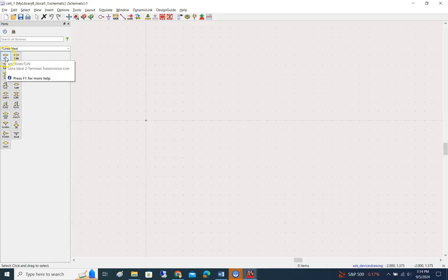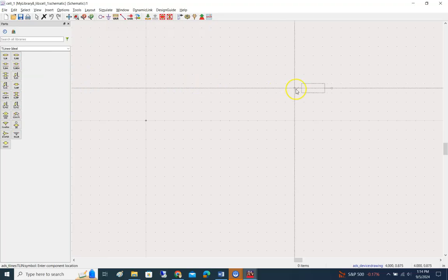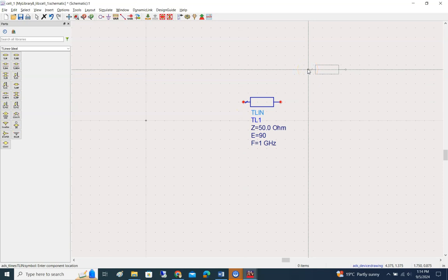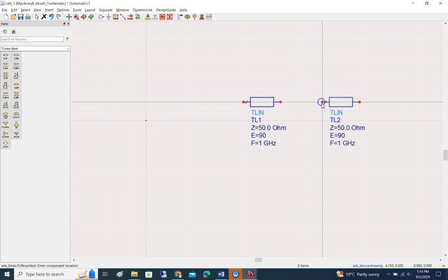We're just interested in this here. The interface is pretty easy. You just left click on that component, come back here, and left click in the workspace. If you click more, it's okay, and if you want to get rid of these options, just press escape. Since we need only one component like this, deleting is also pretty easy. Just click on that component and press delete.